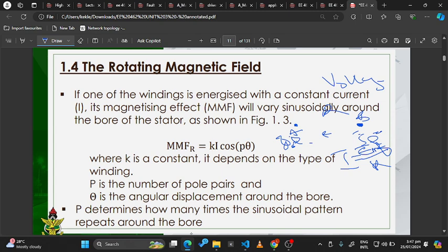Is that okay? In the same way, the same thing happens in a magnetic circuit. In a magnetic circuit, we don't have current flow, but we have what? Flux flowing. So these fluxes, when they are flowing in the magnetic circuit, also encounter opposition. But in a magnetic circuit, we call this opposition reluctance. Okay, we call it reluctance. So the smaller the reluctance, the more flux flows, just as the lower the resistance, the more current will flow.